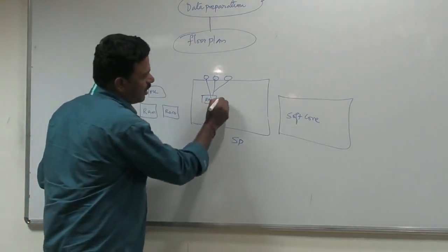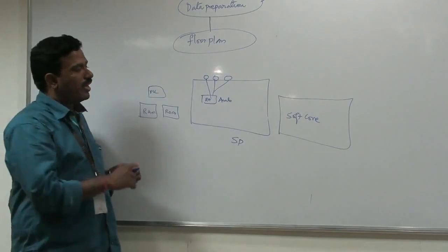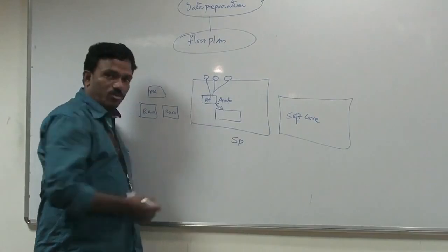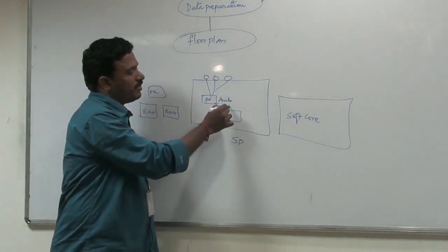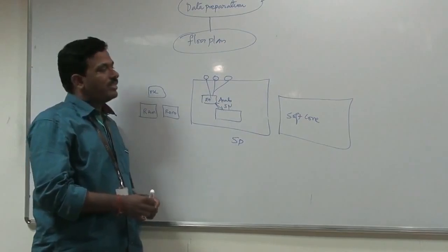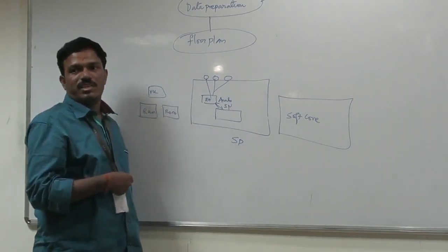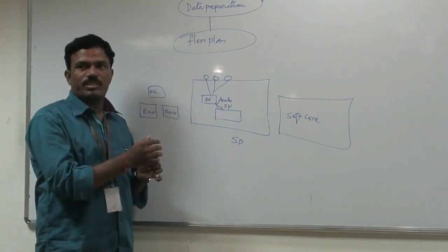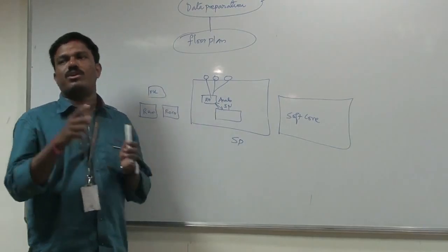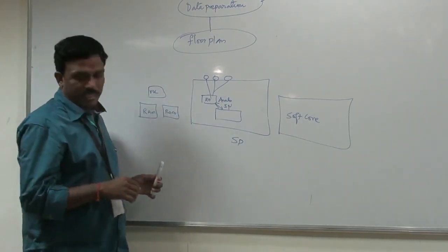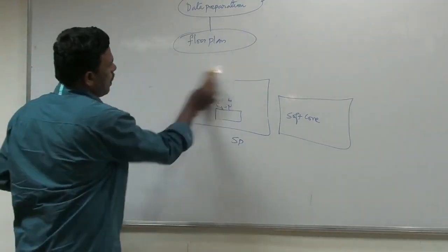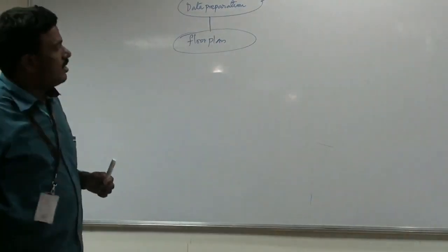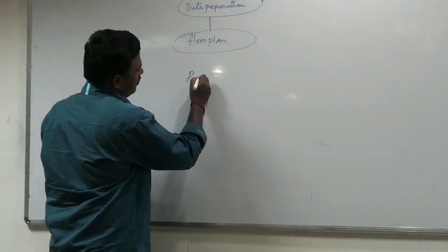And also, suppose this is my analog block. I just want to place some memory very close to this fellow. We need to have certain distance between these macros and macros, so minimum say 5 micron. Right? So all these considerations we have to consider and we have to go for the floor plan. Assume you finished all your floor plan, that is, you identified the right locations for your components. So that is floor plan is over. So a lot of precautions are there, we have to consider and do the floor plan. The next one is called power plan.